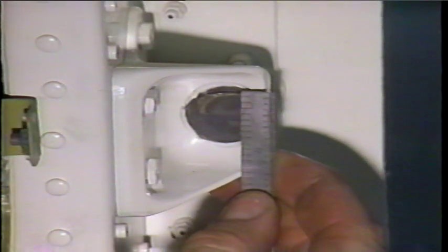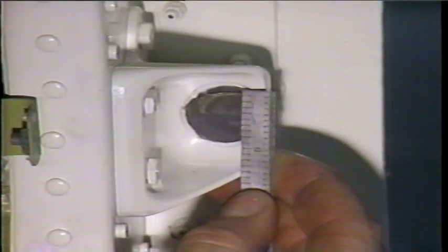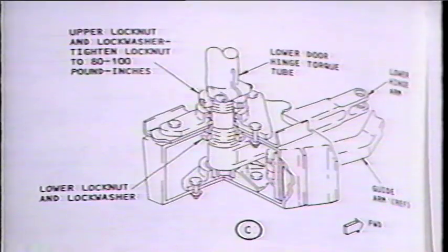On new and replacement doors, excess skin material may be trimmed as necessary to obtain the required skin gaps at the sides of the door. Check that the stop pins are concentric within tolerance with respect to the stop pads before doing any trimming. When this adjustment is complete, tighten the upper lock nut. Lock a tab on each lock washer at the upper and lower lock nuts.